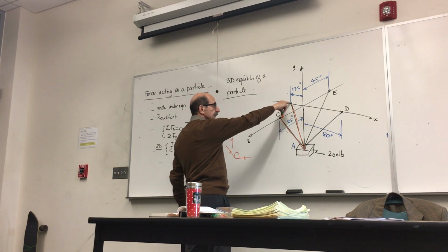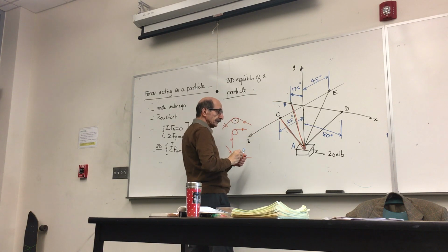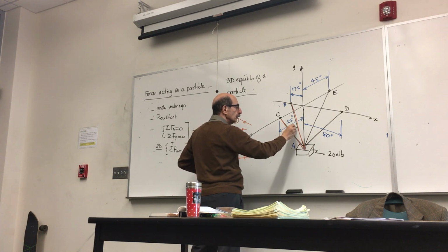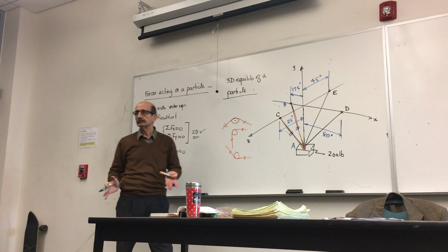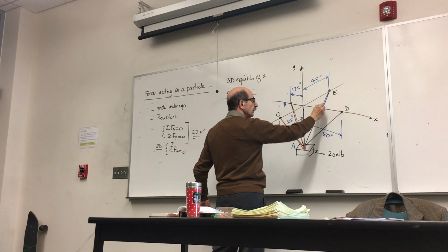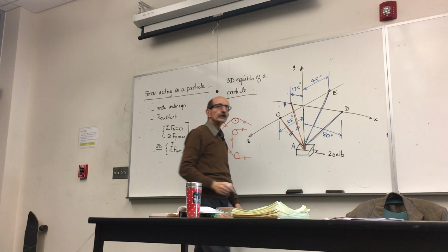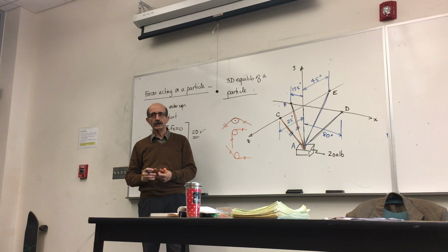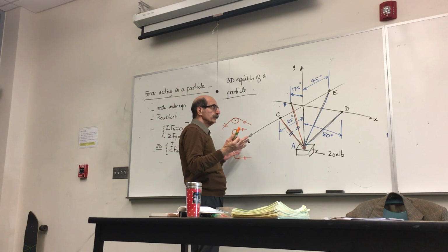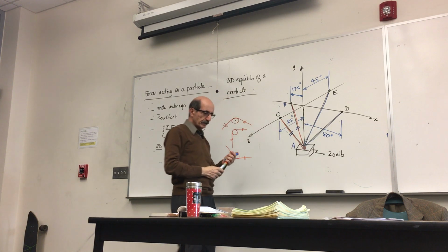The problem states that this cable is a continuous cable going around the pulley that is attached at point A. Therefore, forces in this cable and this cable would be the same. That's what the problem states. But these two cables, this cable and this cable, are tied to this point, so their forces are different. They're not equal. So, in other words, you have three unknowns here. Force in these two cables, this one and this one.